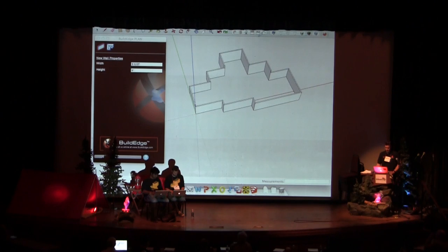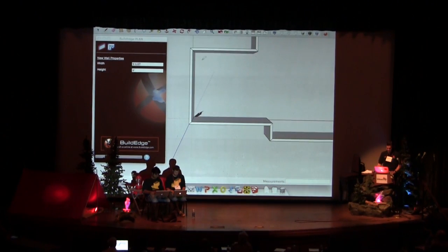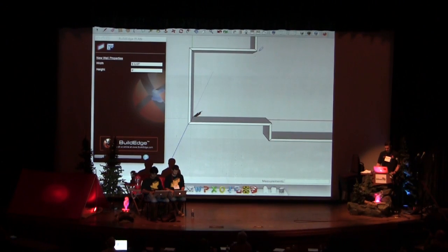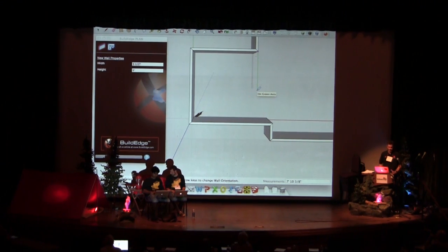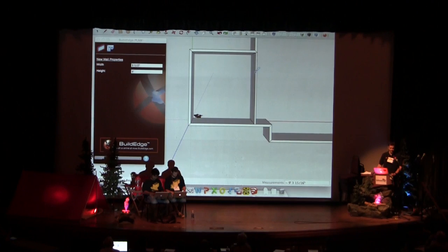I can also use this to put interior walls in. So maybe I'll step to a slightly thinner wall. Say I have 3.5-inch interior walls. So I'll put 3.5, and I'll click to start a wall. And I can actually use my arrow keys to change the way that the wall falls. So I want to fall with the face of the wall over here. And then maybe I want another wall that's 2 feet down from this corner.